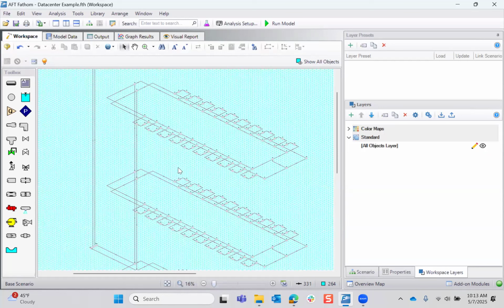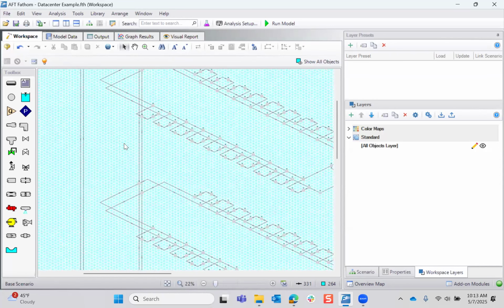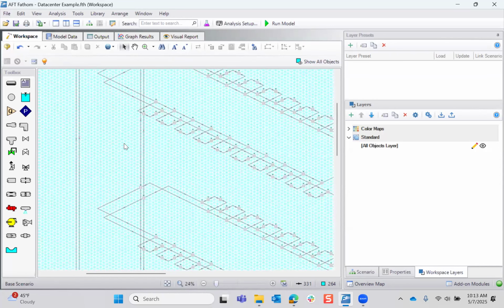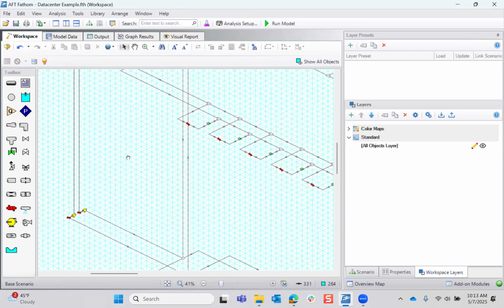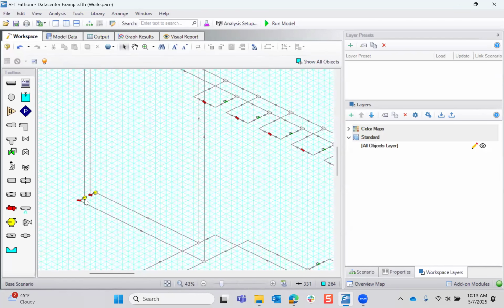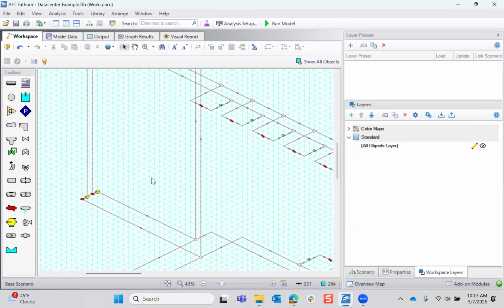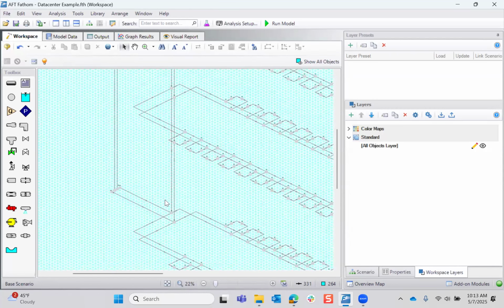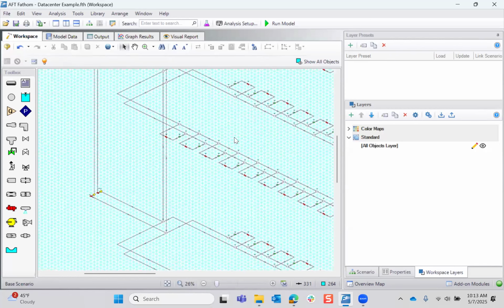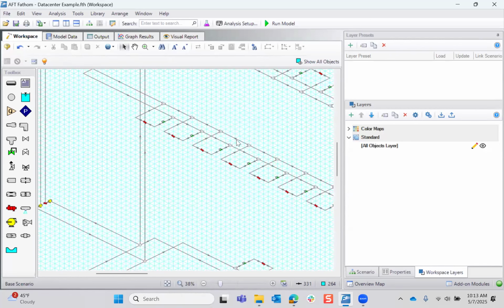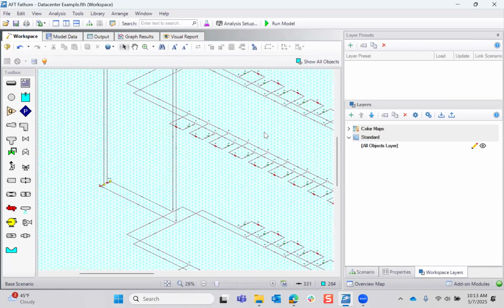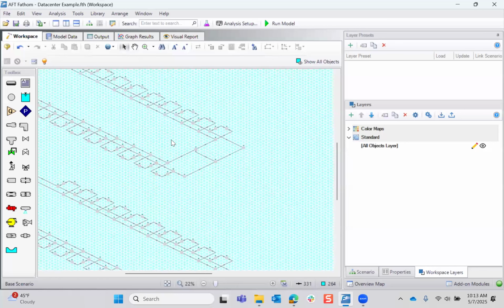The next thing that I had found after I had built out the model, I had solved the issue of the flow rate coming through this model. I had started doing a couple of design considerations. One of the big ones was what happens if I have excess flow coming off of this pump? This was actually a really interesting problem because each of these have a flow demand coming off of them. And if I were to have excess flow, where does it go in the system?